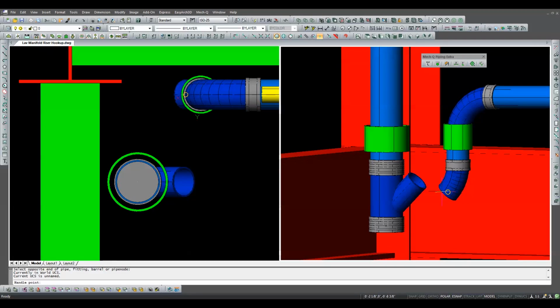We can use any point on the riser for the point to align with. The center of the sleeve, coupling, or pipe would work in this case because their centers are all parallel to the world coordinate system's Z-axis. Now we can see the 3D rotation routine has automatically rotated the elbow to the correct angle. This is because in this case there is only one rotation angle that will allow the elbow's projected center line to intersect the center of the riser. This is obvious when we look at the plan view on the left.